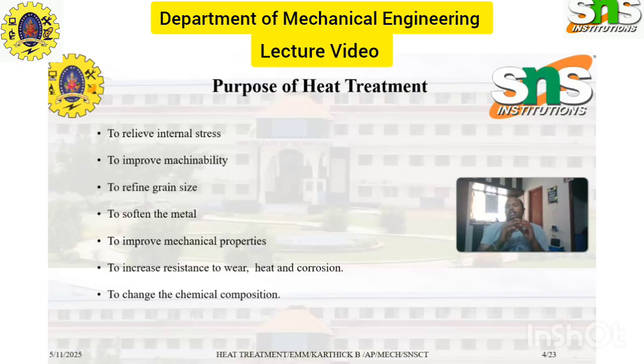So we must note that hot working, cold working, or even stamping, hammering or fabrication work will increase the internal stress in the material. In order to relieve this internal stress, we use heat treatment. Why do we want to relieve it? Because internal stress is one of the major reasons for cracking, failure or fracture, right?